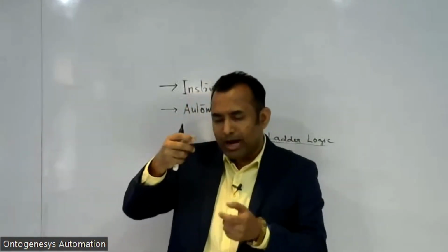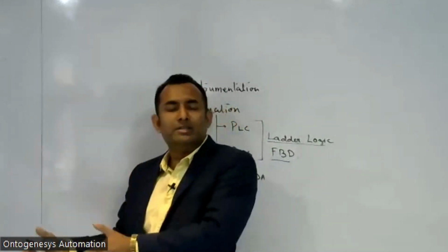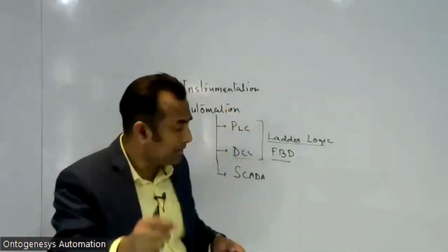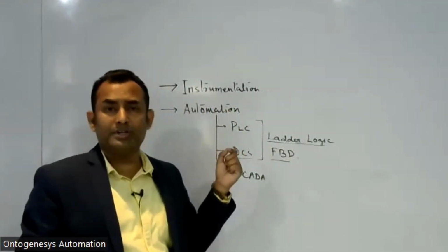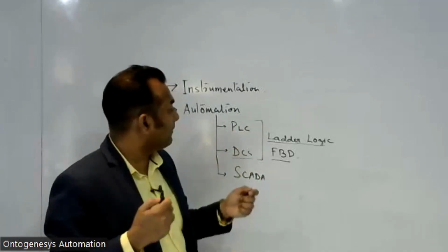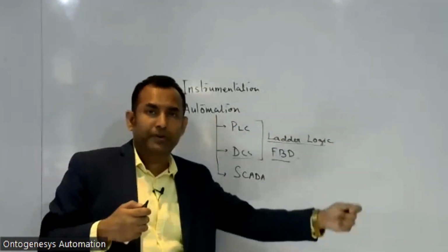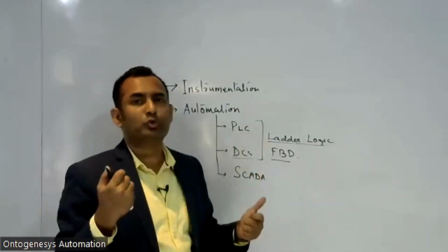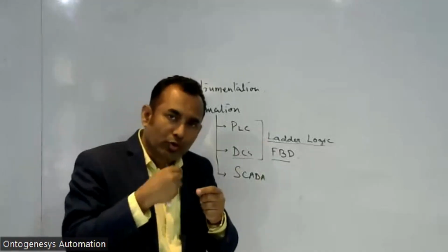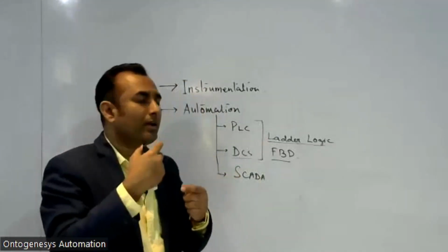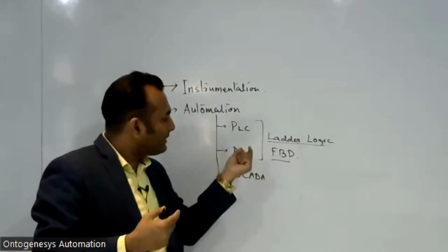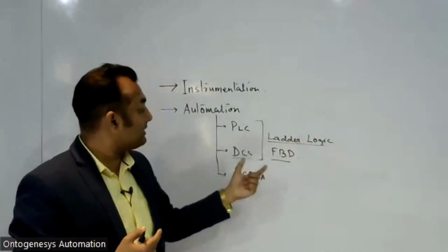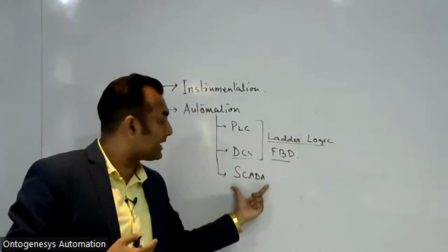So you will be knowing how to calibrate, you will be knowing how to install, and after installation, how to make the wirings of these instruments. You have to draw some cables from the field to your DCS panel or your PLC panel marshalling cabinet. So how to do that part, and then you have to do the tagging, ferrule numbering, and then connect to the channels, then assigning those channels to the PLC, DCS.